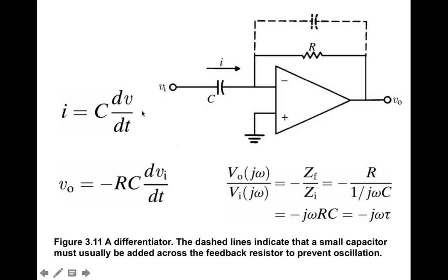You might be taking derivatives if you want to emphasize changes in the signal. You might be taking a derivative if you want to get rid of DC, and for whatever reason the DC offset is variable, and so you can't use a normal biasing voltage or offset voltage that we discussed earlier in the first video. So the differentiator circuit does sometimes come in handy, and of course it can also be used to amplify higher frequency.